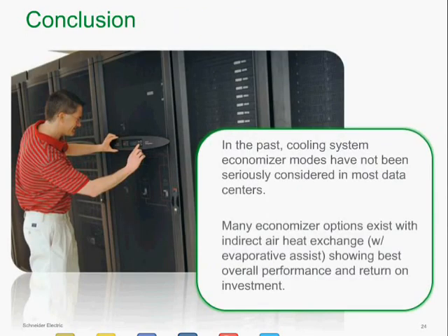So really, to conclude here, I think if you're in a part of the country, whether it be the United States or Canada, where the ambient allows or tolerates the use of economizers, certainly where regulatory requirements are already in place or coming, or whether you're just looking to make your data center more efficient as a whole, there are a lot of different ways to employ economizers in your facility to really drive down your use of power and hopefully lower your energy bill as well.